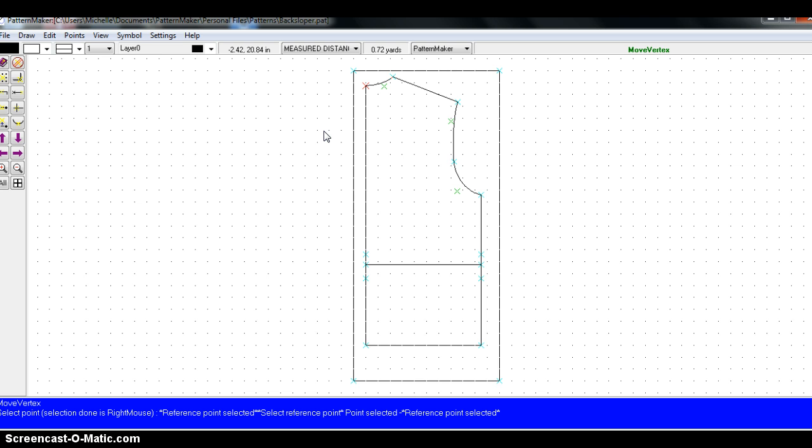Now, much like with the move function for objects, you will be prompted to select more points until you press the escape key or click the right mouse button. We only want to move one point, so let's select our escape key and select Done Selecting. Now, just like the move function for objects, you need to select a base point and a destination. Let's make the neckline 3/4 inch deeper by moving this point from its present location at 1:24.75 to the grid point of 1:24.